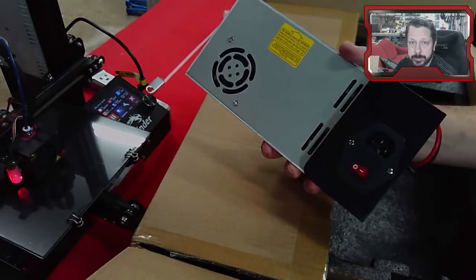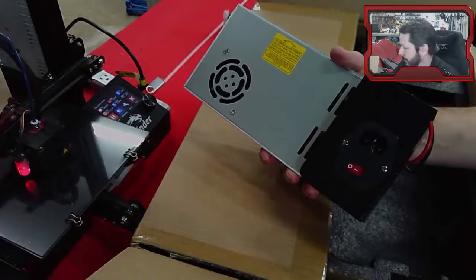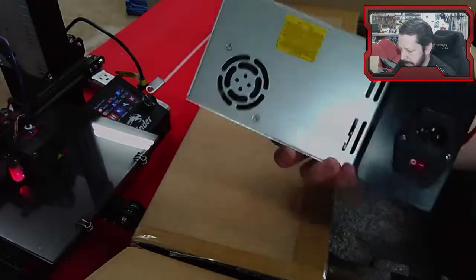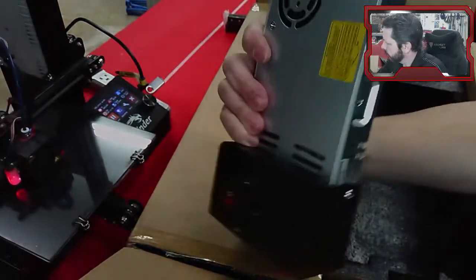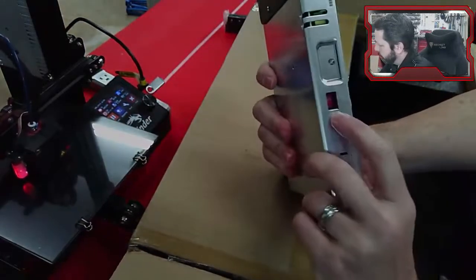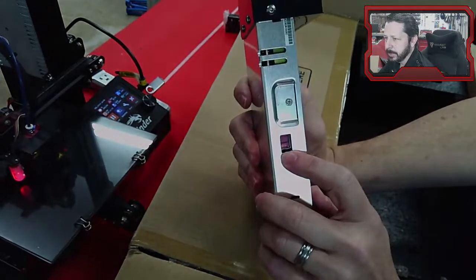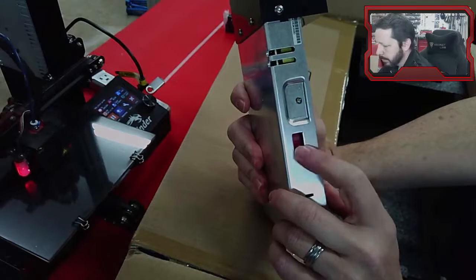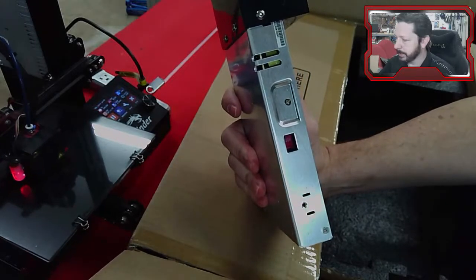What I generally do is I wire it up, and then I hot glue over all those terminals to kind of insulate them. The other thing with these is that by default, pretty much all of them come set up, and this one's the same way, for 230 volts. That switch right there, 230 volts. That's not what in the US we operate at. We operate at 110, 115, 120 volts.